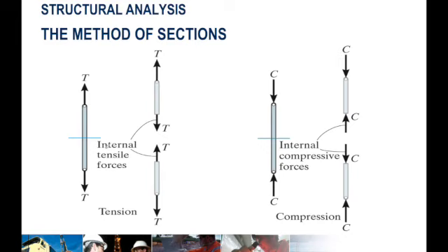Not literally, but just passing a plane through it and doing the analysis. If you pass a plane here and you divide it into sections, this is what it will look like. So the internal forces here will become external forces. So they will act like external loads to your segmented truss.